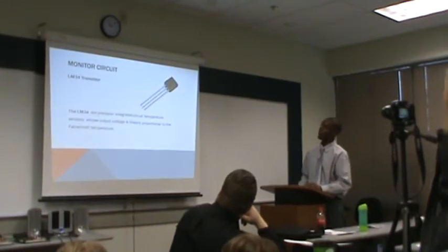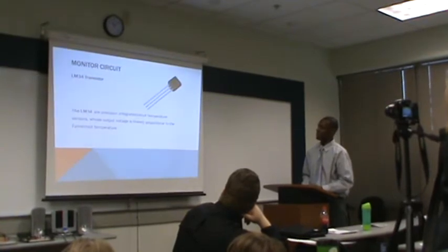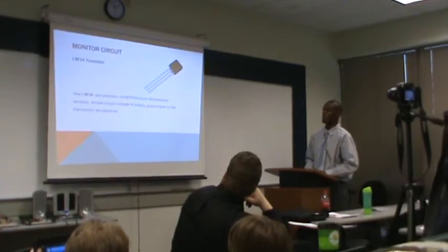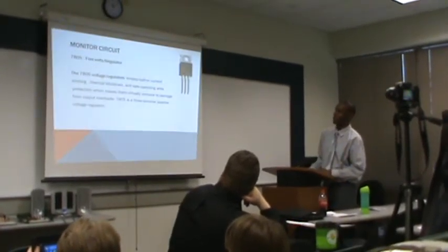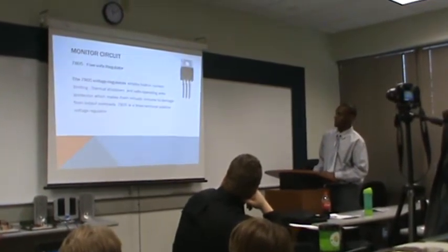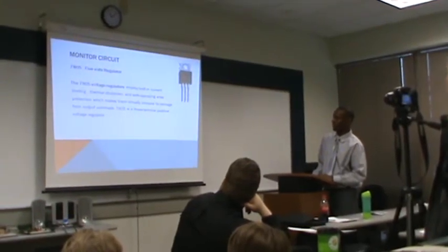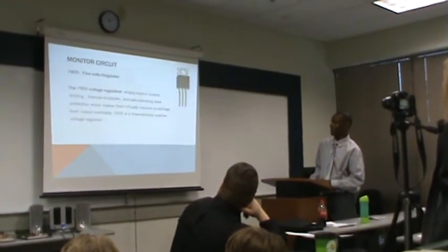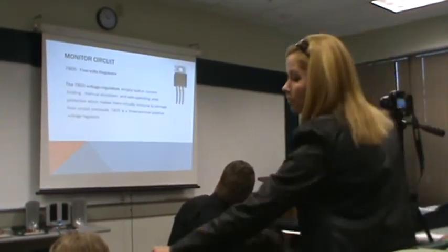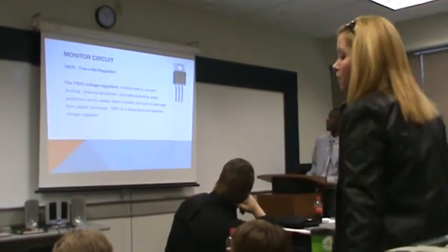The monitor circuit: the LM34 is a precision integrated circuit temperature sensor whose output voltage is linearly proportional to the Fahrenheit temperature. The 7805 is a 5 volt regulator. It has built-in circuit limited thermal shutdown and safe operating area protection, which makes it virtually immune to damage from output overloads. It's a 3-terminal positive voltage regulator.